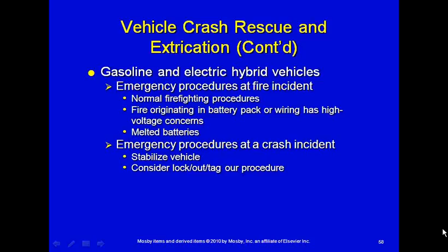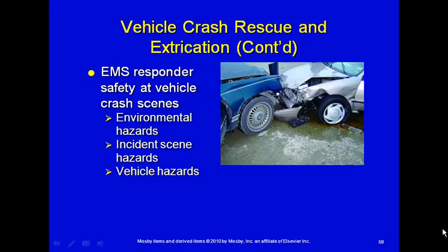As far as the emergency procedures at a crash incident, the vehicle needs to be stabilized. May consider something like lockout, tagout, or some other sort of procedure to check and double check safety before gaining access and before stabilizing the vehicle.